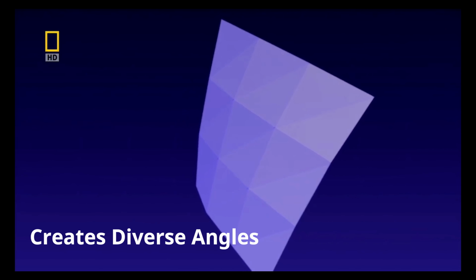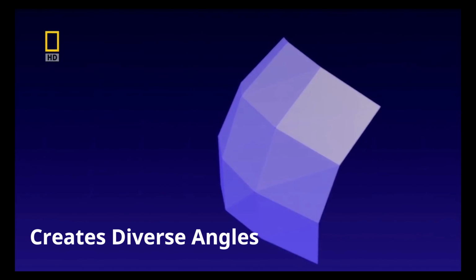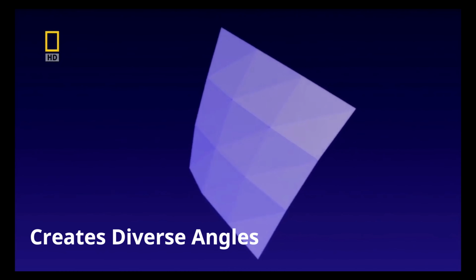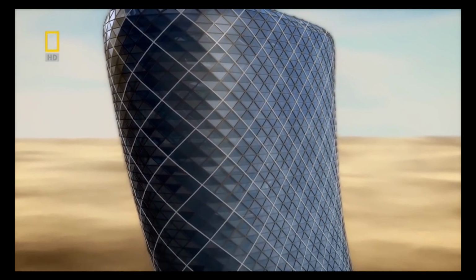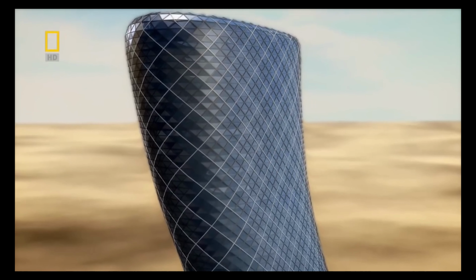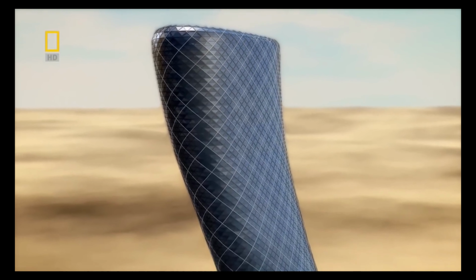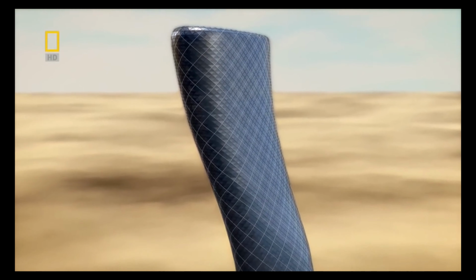Also, they are connected with adjacent glass panes. It means that by making the connection angle between glasses different, they can make every angle of the facade differently. By this, they can make various complex geometric surfaces. With this principle, they could make an iconic twisting facade with a smaller budget.